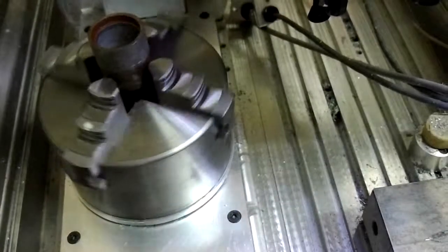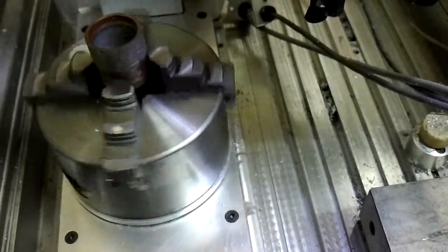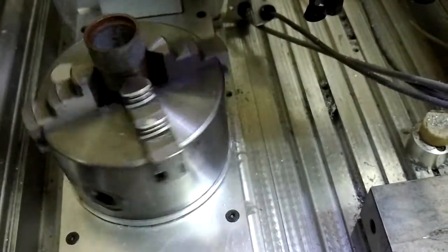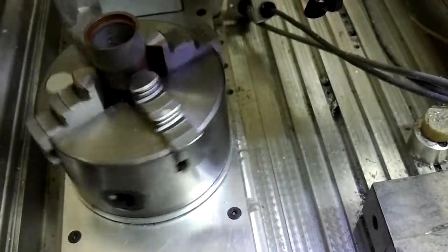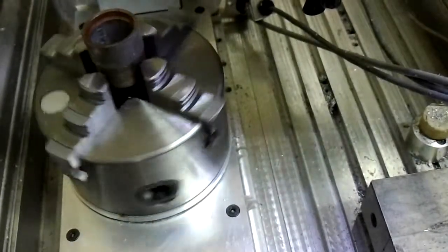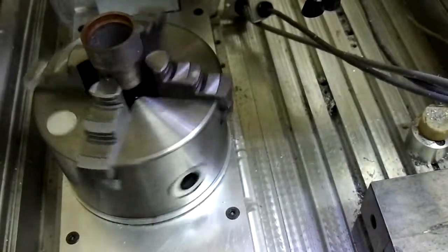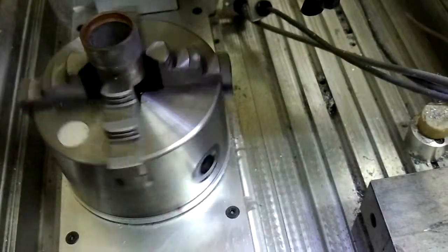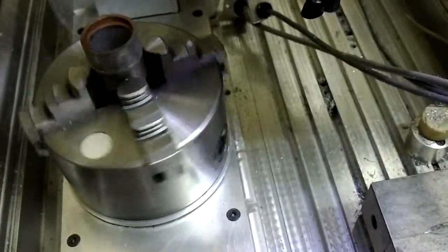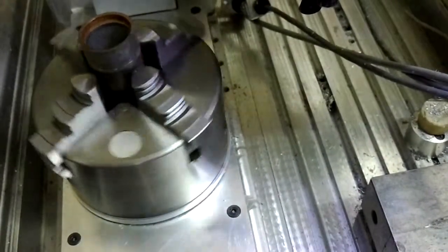This axis has a turning operation. You have to use a fast feed rate on it, and the feed rate will be different from the original 4th axis or X, Y, Z axis. So it's not possible to set 2 different feed rates on the Mark III. So you have to make another separate pulse generator for this 5th axis if you want to use this axis as a turning operation or process.